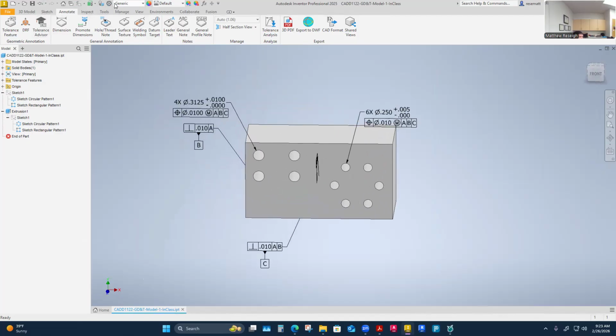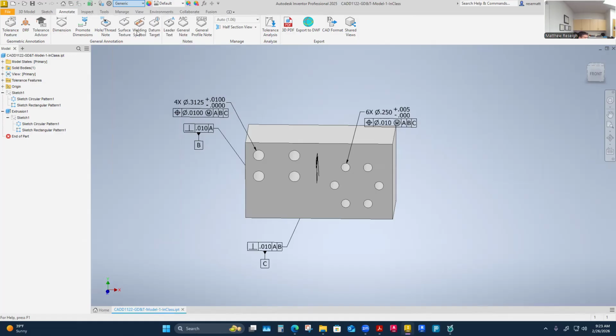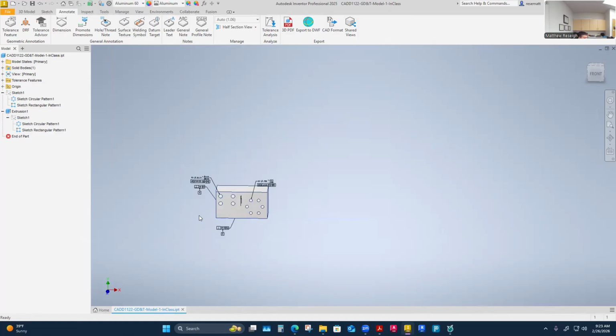The last thing I need to do is this. It's just pick. This is generic by default. I'm going to choose that this is aluminum 6061. Definitely defining materials will be very helpful in a model-based definition. Aluminum, AL, is up here. 6061 is what I have. It's just a type of aluminum. That's a series. I'll just leave it as its default. That way, that's at least captured.